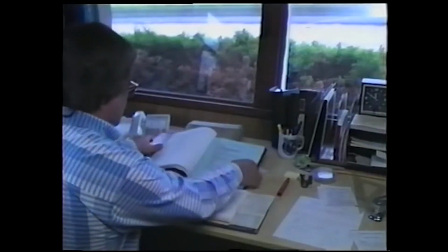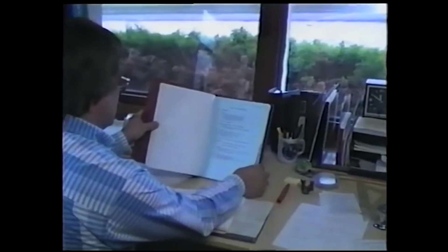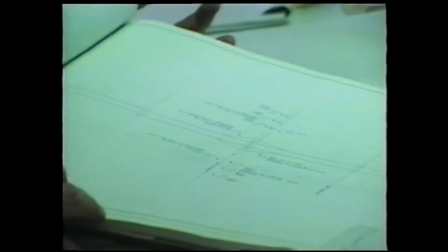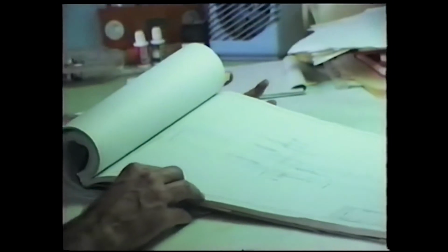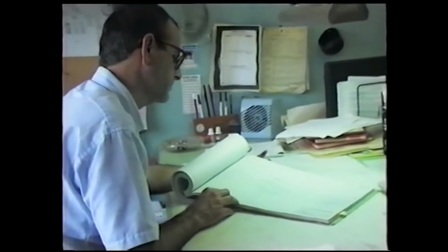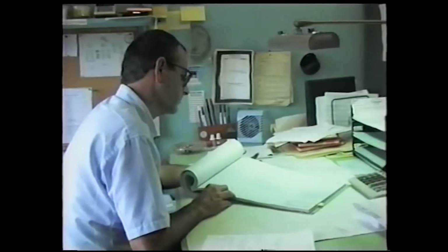Paving details can vary significantly from one job to the next, especially for traffic control. The traffic control plan identifies the types of signs and devices necessary, as well as their placement. So always study it carefully. And remember, no changes should be made to the traffic control plan unless the changes have been approved in writing by your agency.